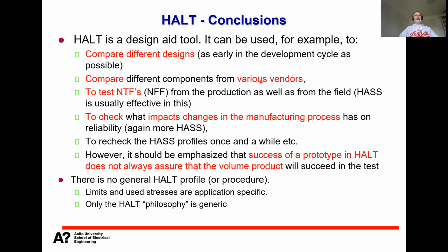And let's say a successful HALT test at prototype level does not always assure nice results in volume production, because the devices you use in the testing can be manufactured in a different way. So the quality of, for example, the connections might be different.